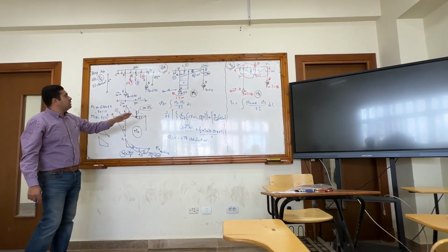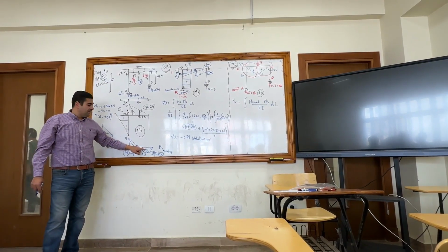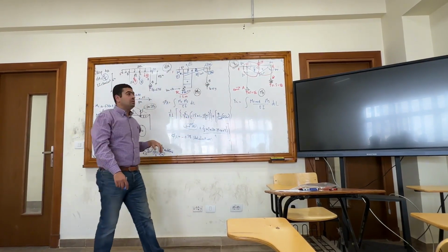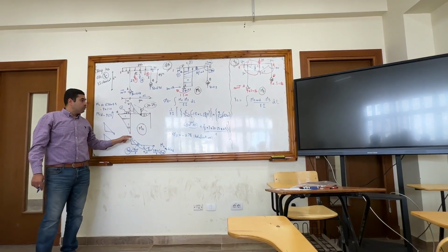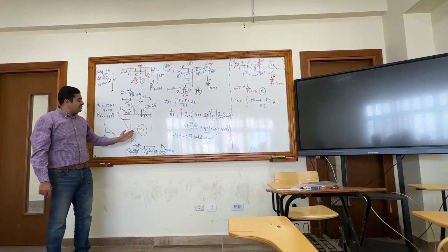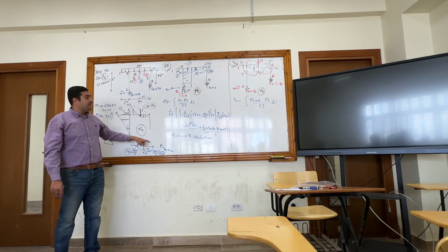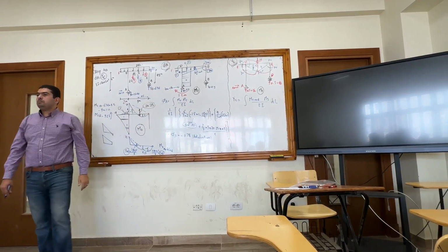And the right-hand side, CE, here will be a triangle and a parabola with a triangle. So for DC, I have two integrations, trapezium with triangle and a parabola with triangle. And for the part CE, I also have two integrations, a triangle with a triangle and a parabola with a triangle.